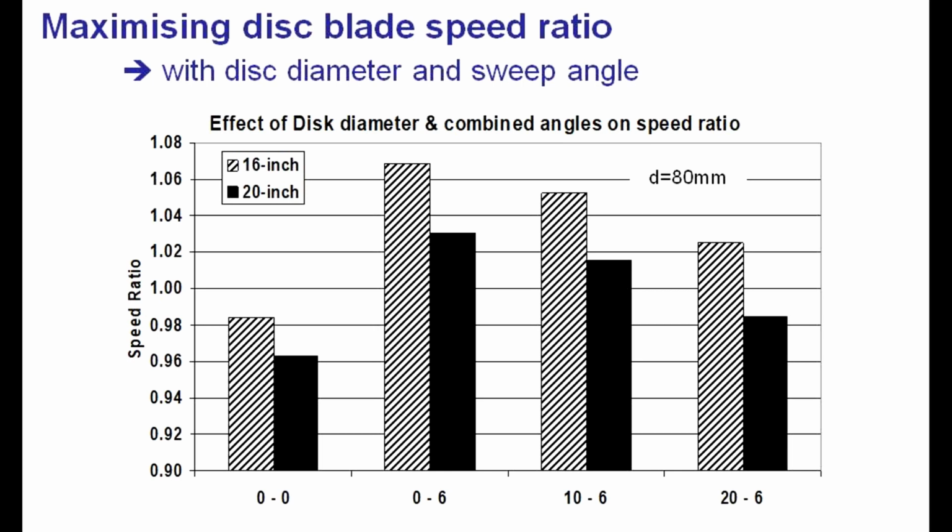On the left is a straight coulter, and then as we put a side angle to it, like a single disc seeder, or we put a tilt as well, we significantly influence what happens to the blade. This is the basis that explains why single disc seeders are typically a little bit better at cutting residue than vertical discs, but when they start to have a tilted disc, they lose their ability to cut residue.